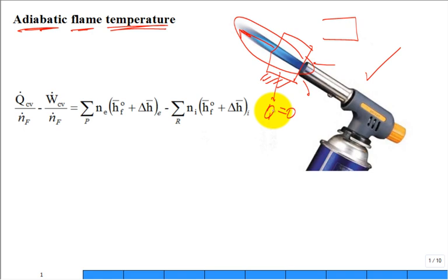They're hotter. Okay. So you start with our energy balance equation. You say no work for sure. No heat transfer, adiabatic reaction. So what does that force this delta H of the products to do? Go way up. And so what you end up with is having an exit temperature which is unknown. But you can use this equation to solve for that exit temperature, that adiabatic flame temperature, where the enthalpy of formations and the incoming conditions, this is all standard. This would be 0. You report it for your fuel all coming in at 25 degrees C.